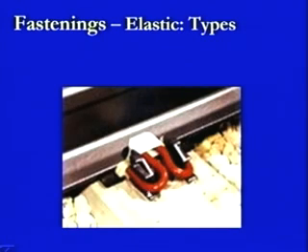We can see in this diagram one of the simple designs of the fast clip. This goes in this form like this. Here there is a connectivity through which it is going. This is the point at which it is trying to put the pressure, and that is where the toe load is getting transferred, and this is another fixture which is to be used so as to fix it in this place, along with one fixture which is used at this location like this.